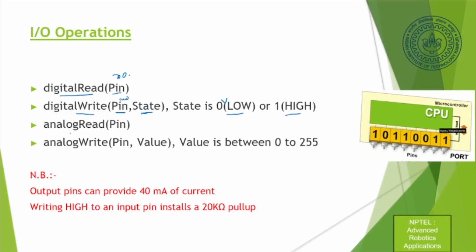Then analog read, pin. Some sensor is connected to some pin number, just for example 10. So I'm connecting the sensor in there. So it understands that whatever is coming into it is a read pin. Whatever is coming will be taken as a read. Now analog write, pin, would basically mean that there's a pin number and it will write in there a particular value.